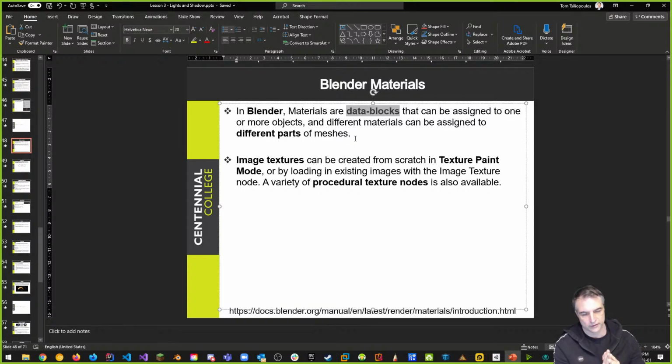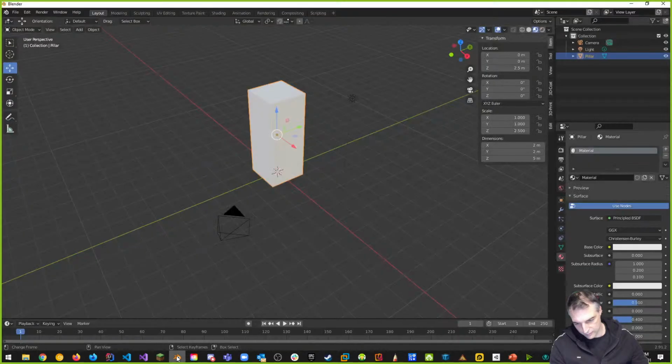And I want you to think about a shader as a mathematical algorithm that allows us to display things like the quality of the light that you're seeing. There is no light, not really. We'll talk about that. But you're seeing a light type effect on a model, and it has to do with the shader that's associated with it. So by default, if I go back to Blender, and don't worry again if you don't understand, by default this is a principled BSDF surface. That's what it is, right?